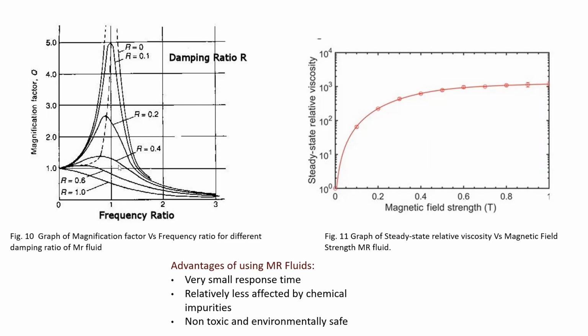As I told you, in a two-wheeler, if I use some SAE 30 oil in our Hero Honda or Bajaj or somewhere, then this damping is fixed. It is not going to change, because we are not changing the oil once we buy the bike for the suspension system. We are changing the engine oil, but not the suspension oil. So this R is fixed. That means we are operating only on this graph.